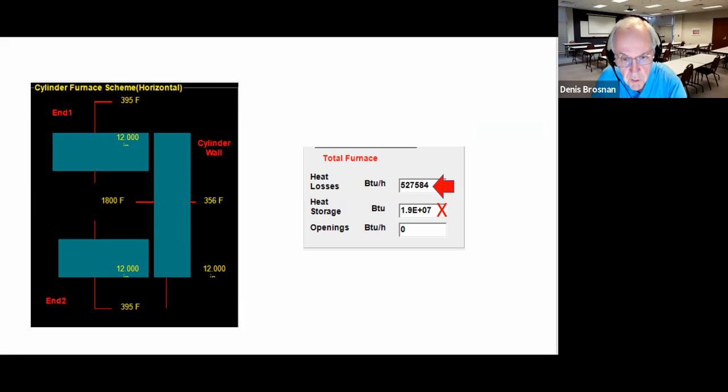And you can see that in this particular instance, we're going to show a pretty high temperature on the rotary kiln shell. Now, people that operate rotary kilns are very concerned about keeping these temperatures below points at which the kiln shell can deform, because that can cause an outage in the kiln.